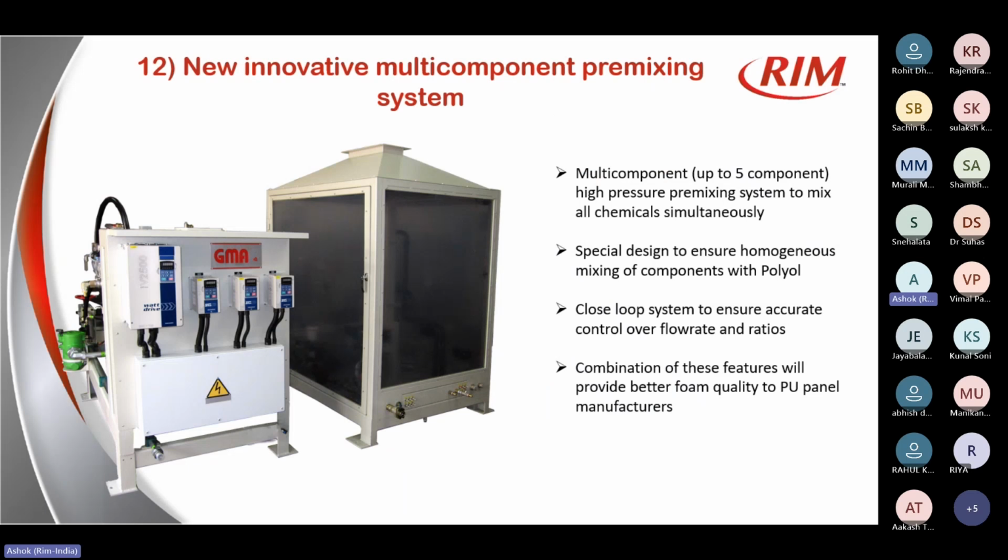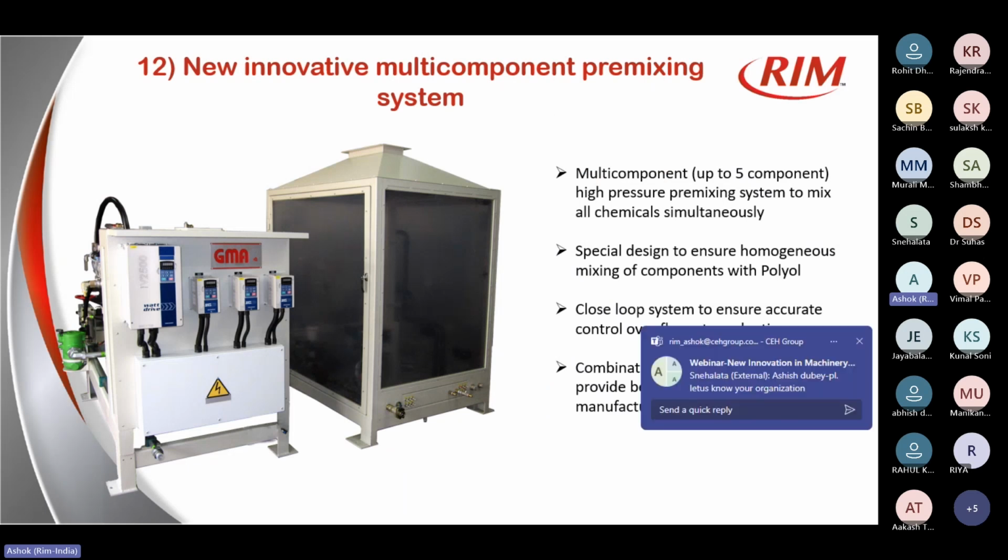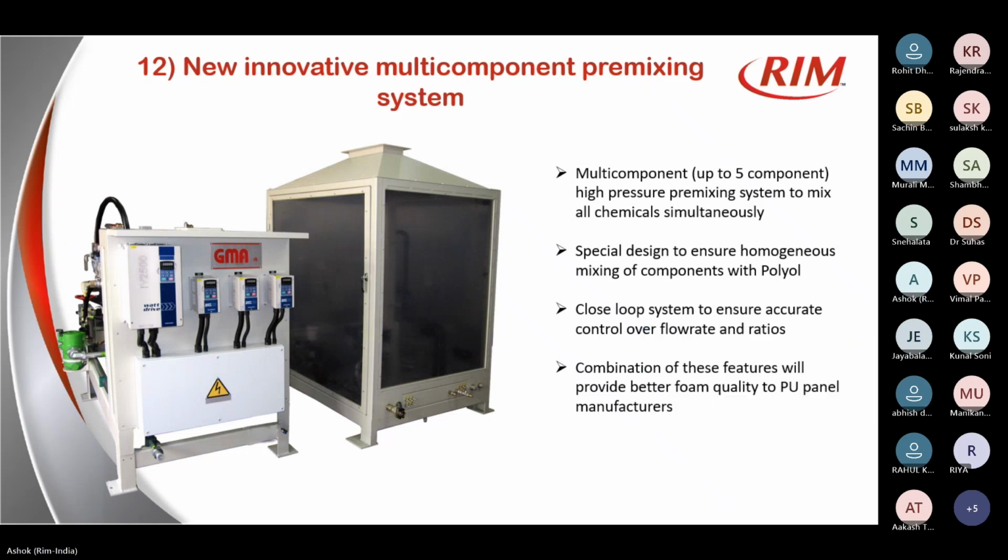When you talk about the new innovative technology for multi-component premixing, there is a multi-component premixing system which mixes up to 5 components or 5 chemicals together simultaneously before it delivers to the mixing head. This design helps to have homogeneous mixing of all the components, especially polyol and cyclopentane or N-pentane.